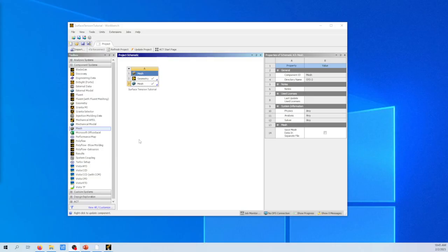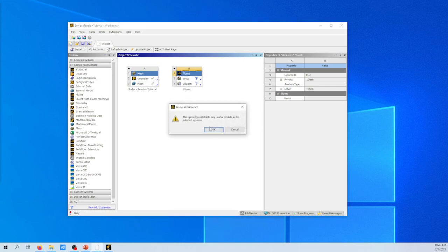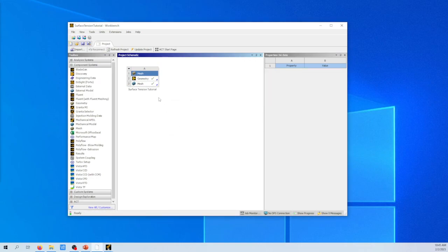All right. Now, with our mesh defined, all loaded up, this is all good. Now, one way to do this is to use the Fluent block. You can also just use the Fluent all together with the geometry and mesh. Now, I have found that I don't save properly sometimes doing that, and it corrupts the entire file while you're trying to solve it.